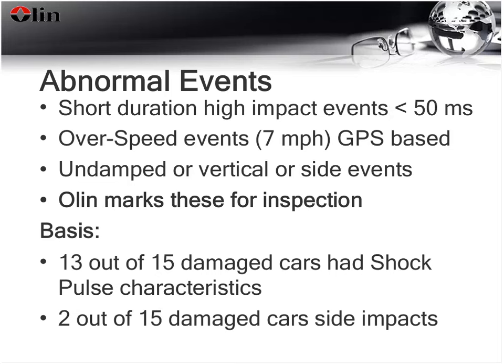And what we look for is short duration, high impact events that last less than 50 milliseconds. Again, it is important to know both the 100 hertz filter reading and the 10 hertz filter reading to be able to determine the duration of your impacts.